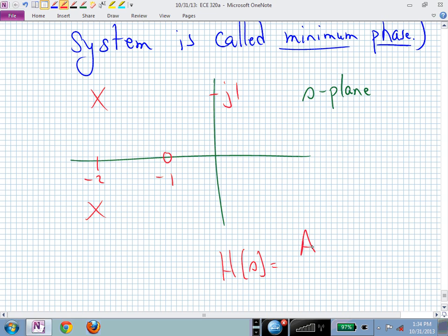We don't know the magnitude, do we? Or the scaling factor, but we do know that we have a zero at -1, and we have two poles that are complex conjugates. They have a real part of -2 and an imaginary part of 1. So they naturally like to shake at 1 radian per second. That's their damped frequency. Their decay is influenced by e to the minus 2t, and the zero is at minus 1.